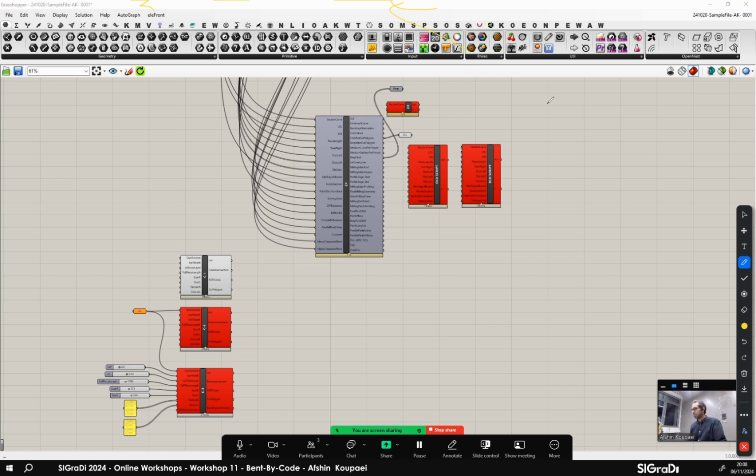Addresses like these curly braces: you say {0}, or {0,1}, or {0,1,0}, and then {0,1,0,2}, and then {0,3}, or whatever. So you can have all of these sub branches inside Grasshopper. If you want to transfer information and talk with Grasshopper in this sort of data structure, you have to use data trees.